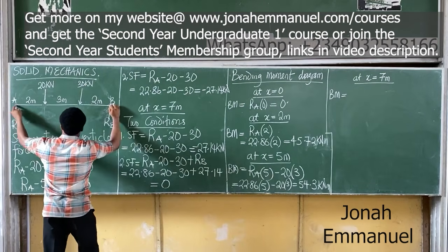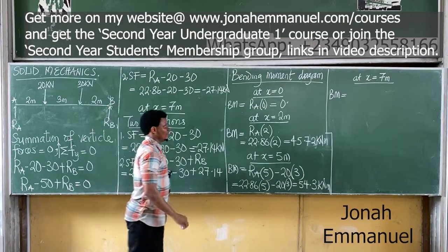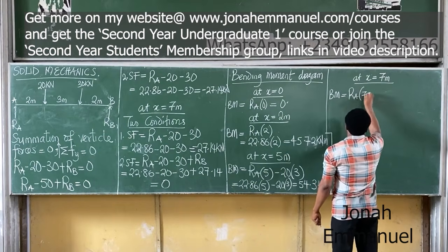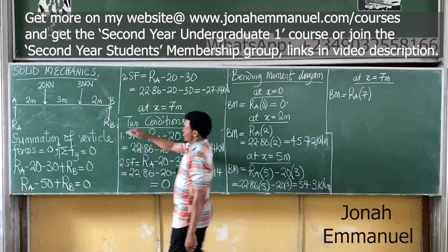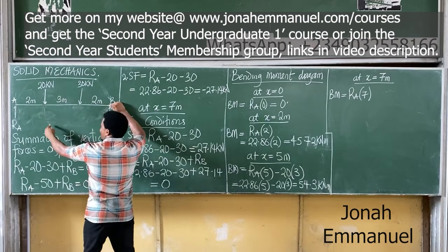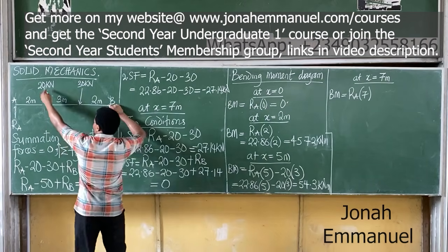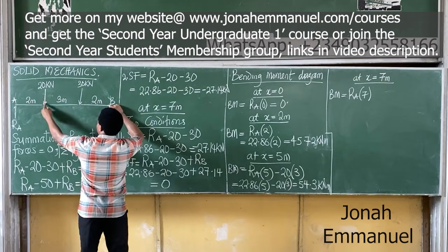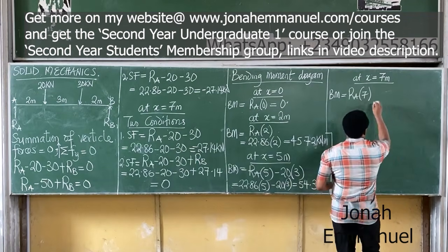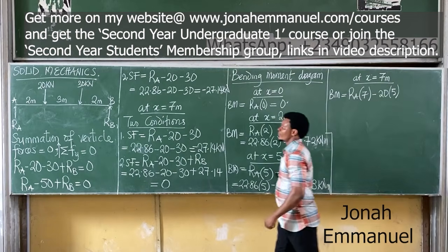It becomes RA times the total distance, 2 plus 3 plus 2, that's 7. So RA times 7. That moment is checked. Next up, this moment is coming down this way. This is what there? Anti-clockwise. It becomes what there? Negative. Negative of the force, which is 20. Distance from here to here is what there? 5. Negative 20 times 5.